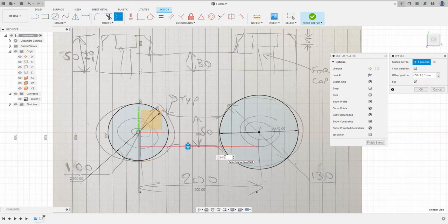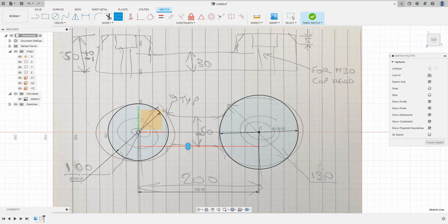It means that if somebody comes to see this later and has a look at the sketch, they'll see how I've calculated this. I've worked from the 50 wide dimension and just halved it as per the requirement on this sketch. This is simple. Obviously I could quite easily put 25, but with more complicated dimensions, this is actually quite useful. Press return. That adds the offset line.